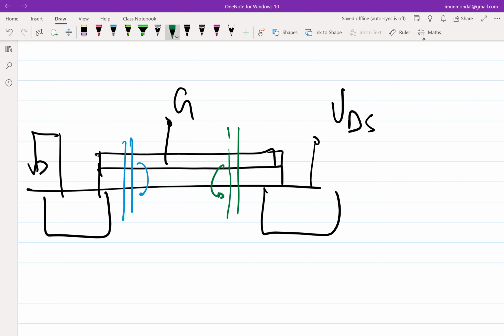Can you comment on the effective voltage across the oxide between these two slivers, the sliver on the left and the right? More on the left. Because the gate voltage is constant for both slivers, but the channel voltage here is lower than the channel voltage here. So you expect more mobile charges on the sliver on the left than on the sliver on the right.